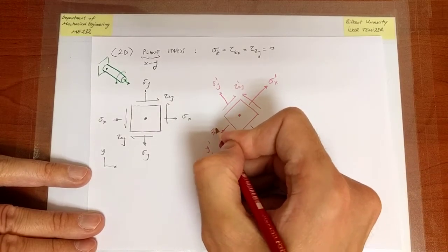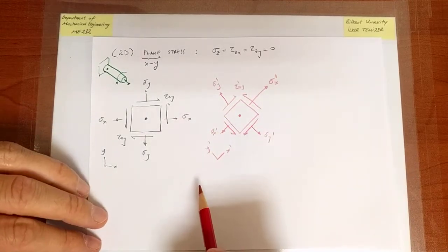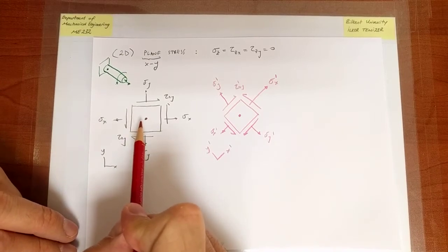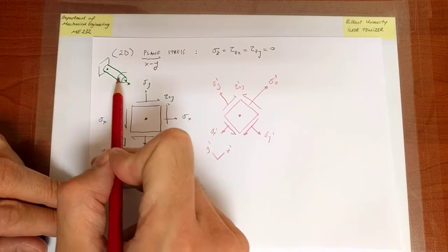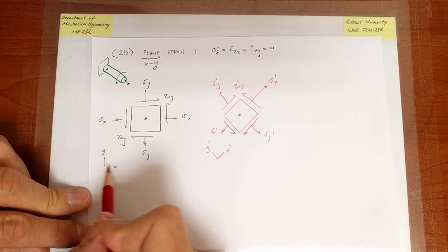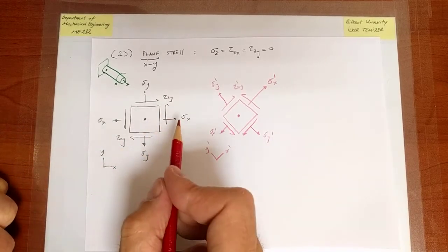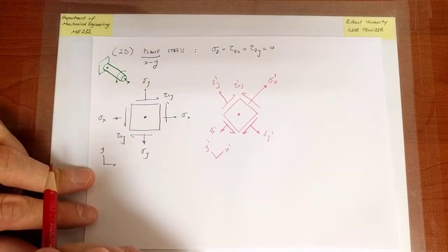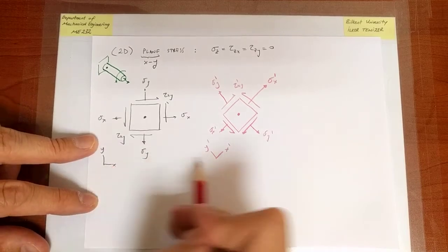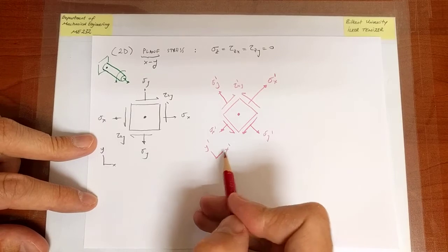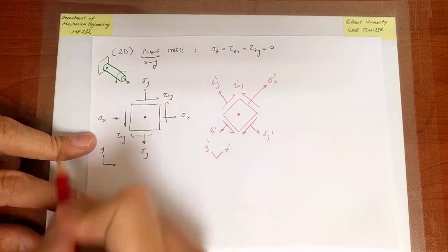And so that's the way the picture is going to look. Okay. And now the question is, suppose I give you this, for a given state of loading, typically the orientation of the structure dictates what these axes choices are. Say, in this case, let's say the x direction is the axis of the cylinder, and so it's clear what I should choose it to be. But now I'm interested in the question, if I had chosen it to be some other direction, then how would the components of the stress change at the same point that I am looking at?